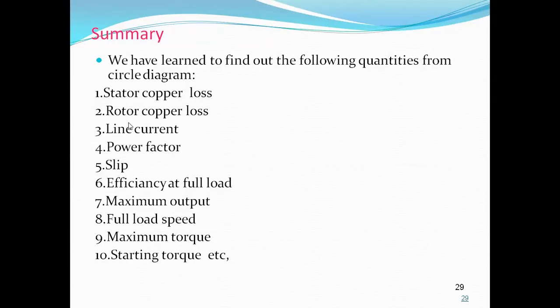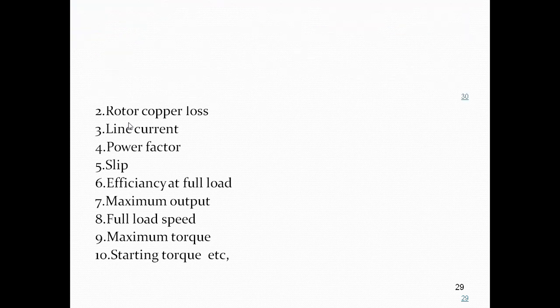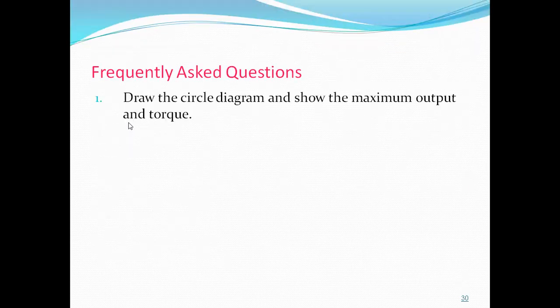These parameters we can calculate from the circle diagram. Note down this: stator copper losses, rotor copper losses, line current, power factor, slip, efficiency at full load, maximum output, full load speed, maximum torque, starting torque, rotor efficiency, motor speed. That one also we can calculate.